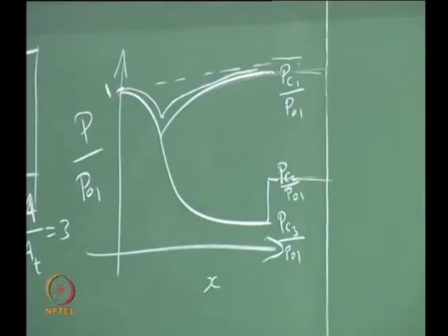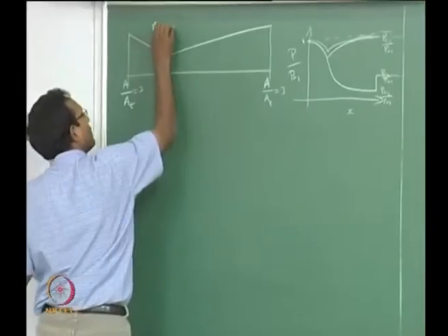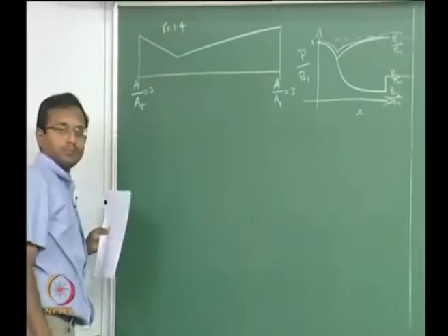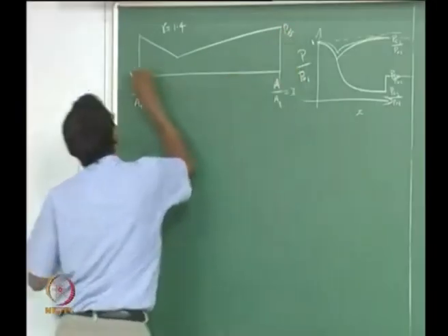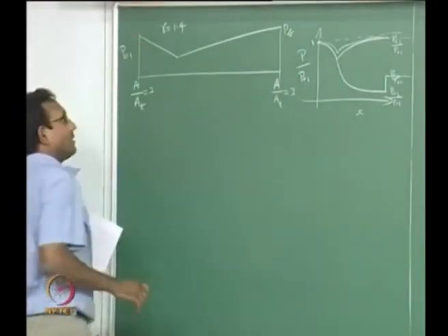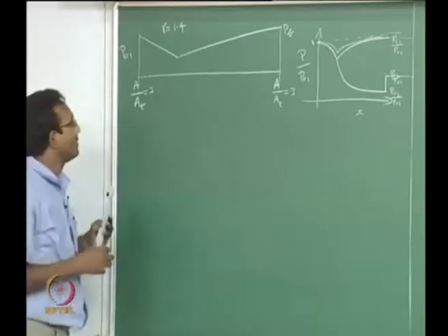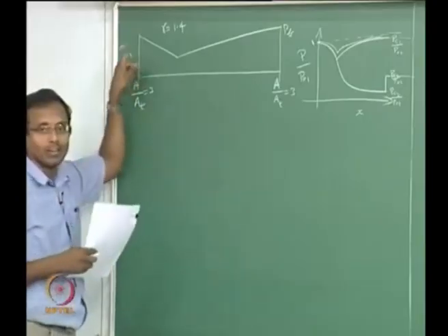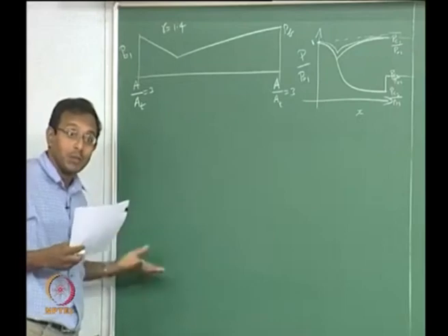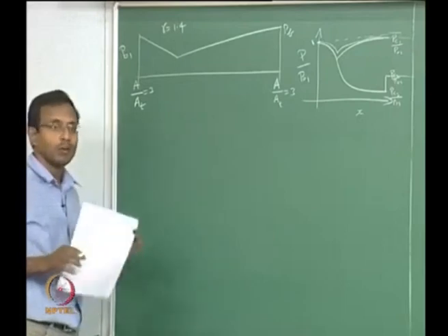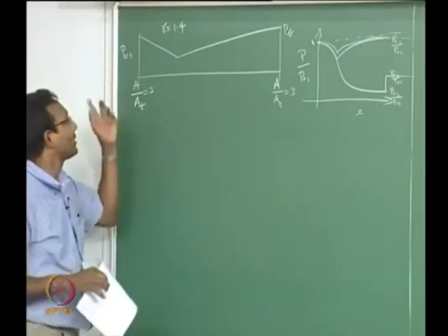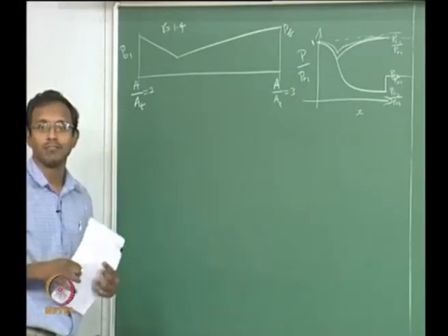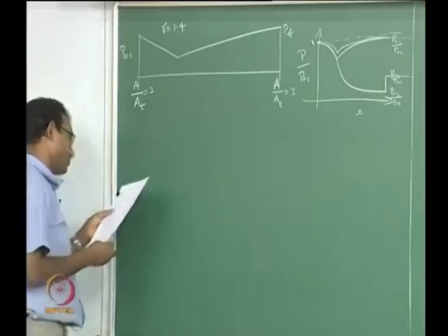We will just pick up that particular case. I am going to assume gamma equal to 1.4 for this problem. I am going to say there is some Pb back pressure and some P01, and since we already discussed that if I want to change the Pb by P01 ratio, I could either decrease Pb or increase P01. We won't worry about what experiment I am really doing. All I will worry about is that I am getting a particular ratio Pb by P01. I will just work with that for now. That should be enough to do stuff.